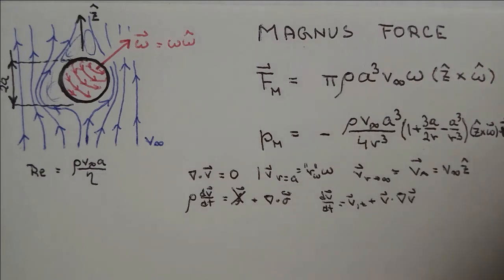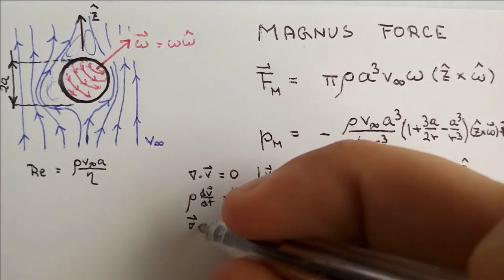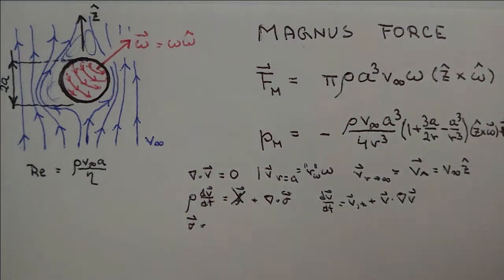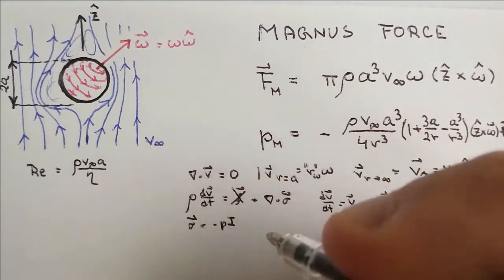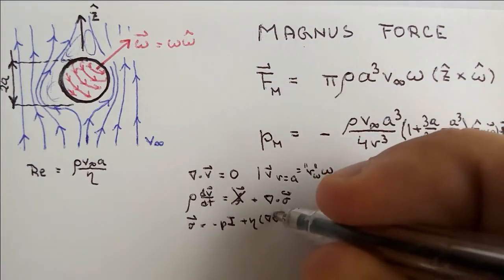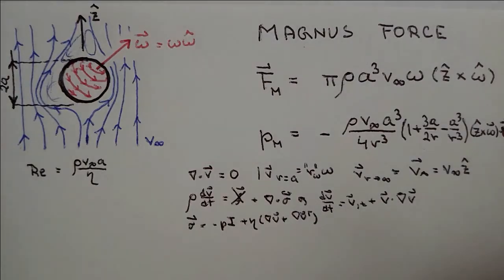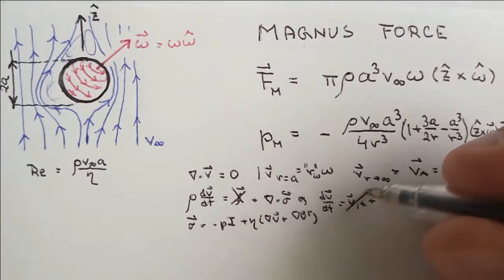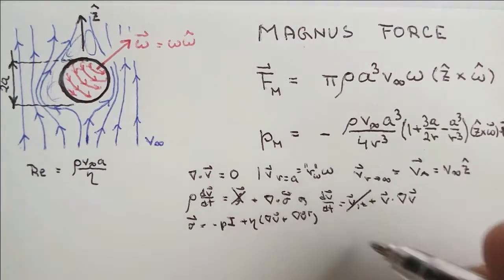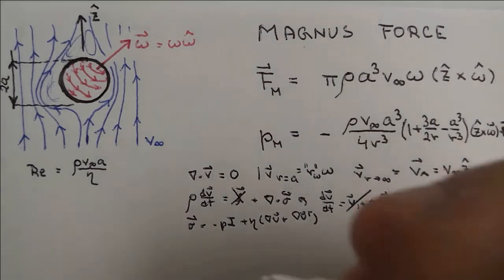If you substitute into the constitutive condition, which reads, for an incompressible Newtonian fluid, minus p times the identity matrix plus eta times gradient of v plus gradient of v transpose. If you substitute in, you will get, stationary, because I will dismiss this term, I will cross it out and forget this term, because I will assume that the flow is stationary, there is no turbulence there.